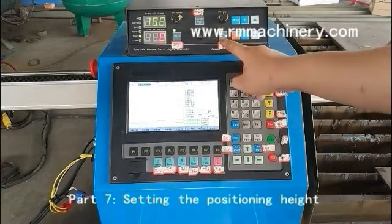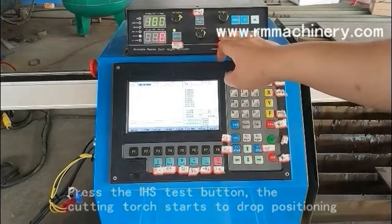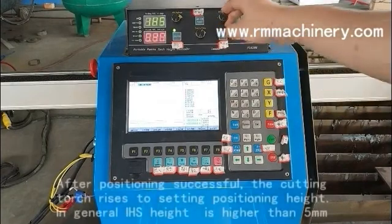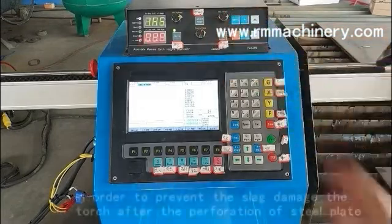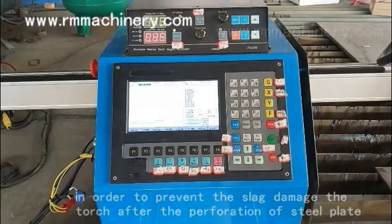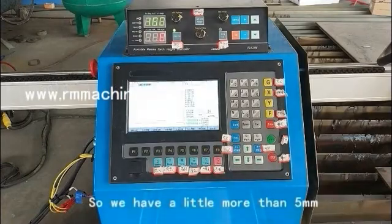Part 7, Setting the Positioning Height. Press the IHS test button, and the cutting torch starts the drop positioning. After positioning is successful, the cutting torch rises to the setting height. IHS height is generally higher than 5 mm, in order to prevent slag from damaging the torch after the perforation of the steel plate. So we have a little more than 5 mm.